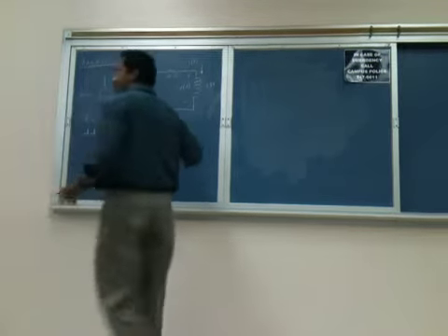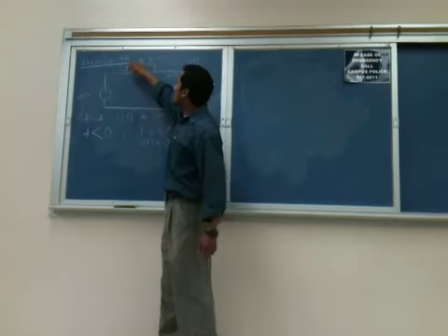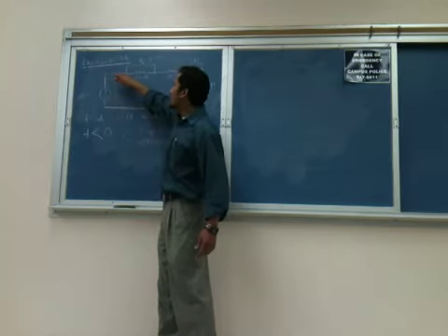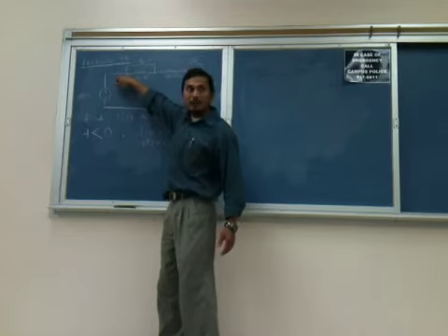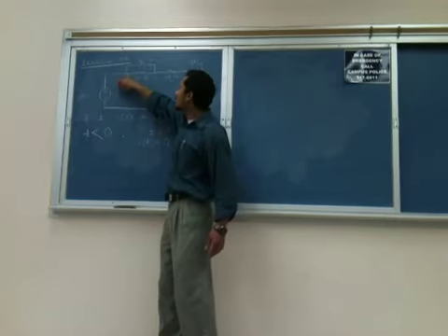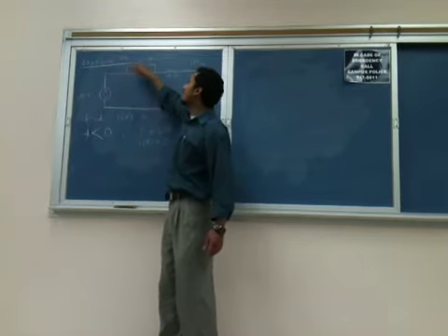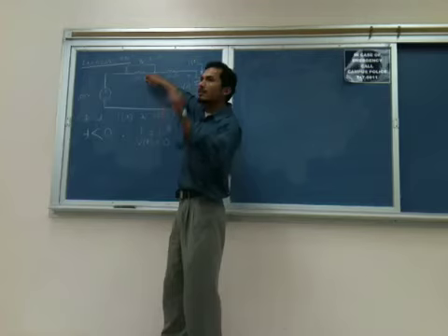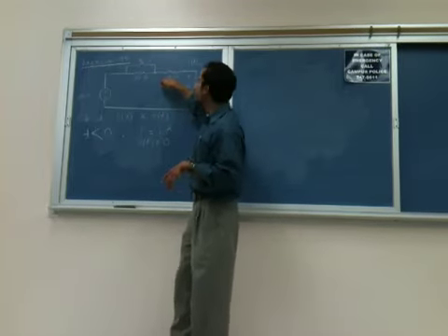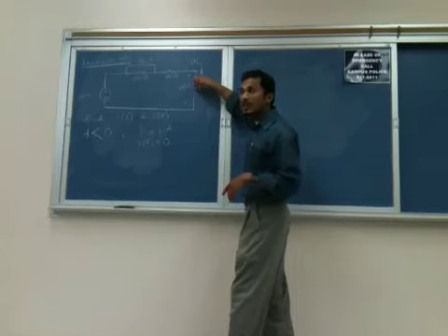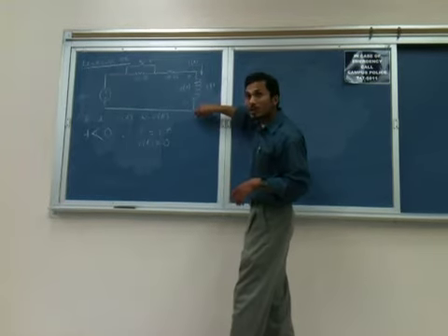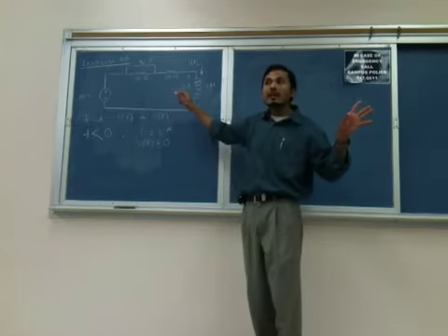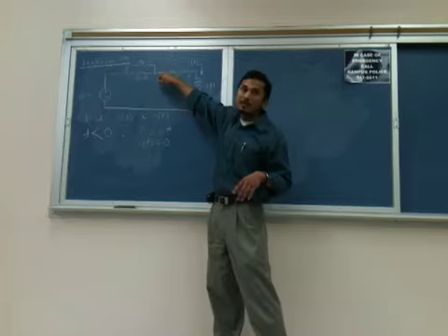So, the idea is, once the switch was closed, the current is going to be generated from here, then it's going to come over here, and it will always take the path of least resistance. So, instead of going through this path, it's going to go the other way around and bypass this resistance. Then it's going to see only one resistance, that is 100 ohms. And finally, since this was a steady state condition, the inductor will also be a short. So the only resistance that the current will feel is the 100 ohms resistance.